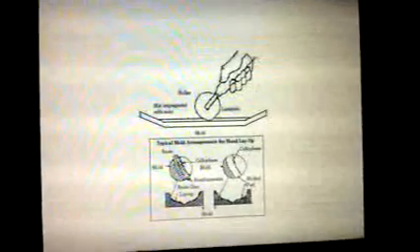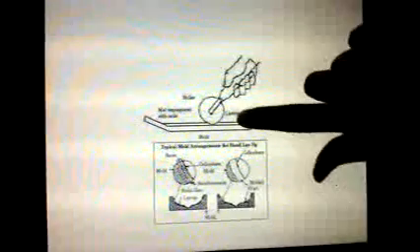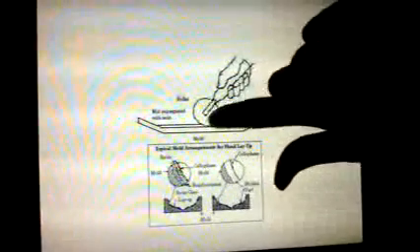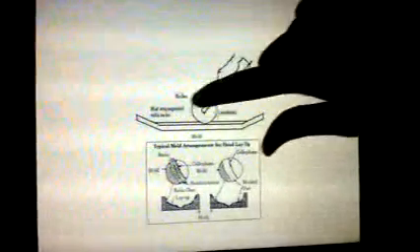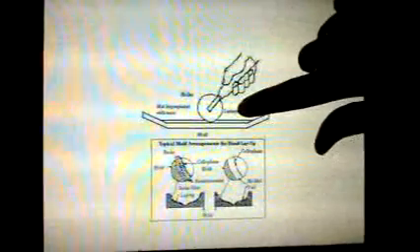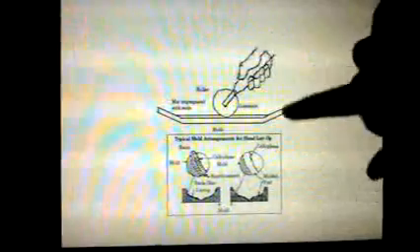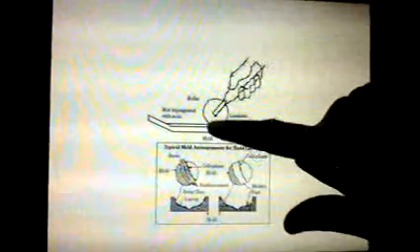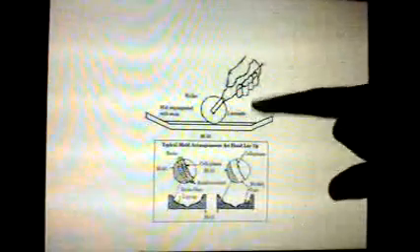This is the hand layup technique. This material here is called resin. This is a brush applied with resin. While rolling, we will be applying uniform matrix and resin. After completing one layer, we will apply another layer.